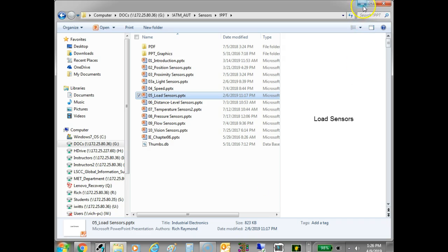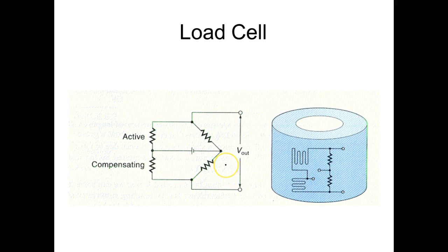Very few of us deal with strain gauges. What they do is they confine all this circuit, your Wheatstone bridge. So here's your Wheatstone bridge. Here's your strain gauges inside this big old unit. And this is what they refer to as a load cell. So the load cell is the combination of the Wheatstone bridge. It's actually in there; you don't see it. All you got is 4 wires. 2 of them they call excitation. 2 of them they call output.